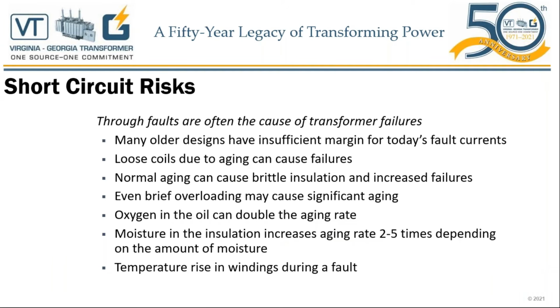Let's start summarizing short circuit risks on this slide. However, before I start summarizing, I want to emphasize that short circuit forces are not the only mechanical forces that the transformers see. There's, of course, the transportation forces during shipping and handling of the transformers. So we, as manufacturers, must design and build the transformers to withstand the mechanical forces that they will see during transportation. How we anchor the core and coil to the tank, the cover, the bottom, the sides, and all of the above is very important.